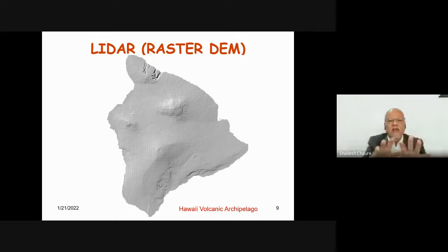But because the information of elevation is available, from this we can compute a hill shade model. Suppose there is a topography like this and the light source is here. So this part will be illuminated, the other part will have the shade. And depending on the sun angle and the height, the shaded areas will vary, the intensity of shades will vary, the brightness of the slopes and the surfaces will vary, because it depends on how they are oriented with reference to the light direction.